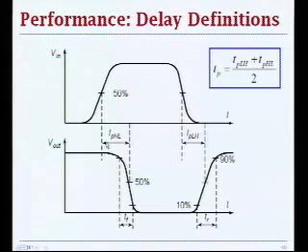So this defines your falling transition, and the delay experienced by the falling transition at the input, which will cause your output to undergo a rising transition, is called TPLH. These two delays really have some physical meaning because that's the time it takes to produce a falling or rising transition. And oftentimes we also compute the average of the two delays, and then we say this is a propagation delay associated with the gate. Although this number has no physical meaning, it provides you a relative ability of a gate in terms of gate delay, in terms of speed for that technology.